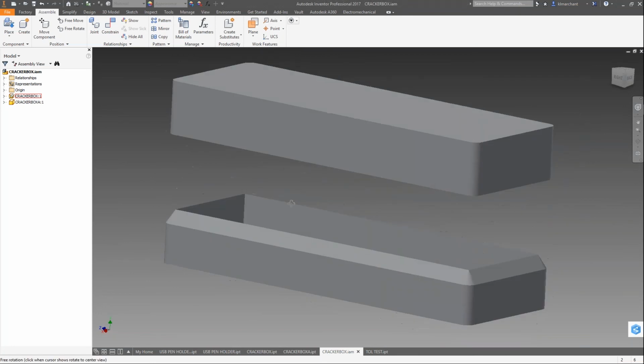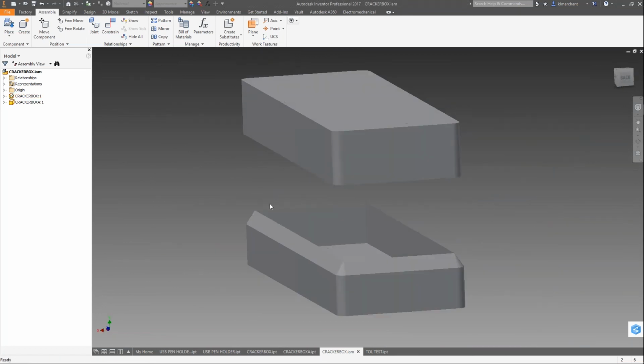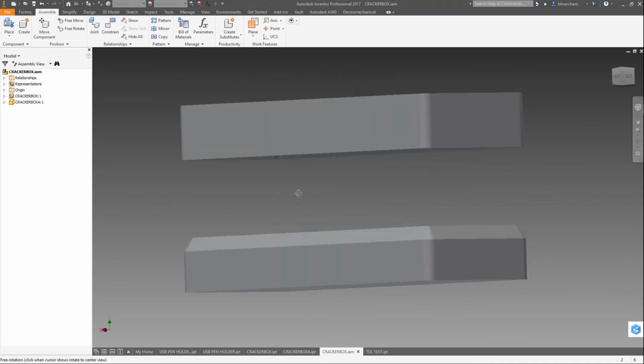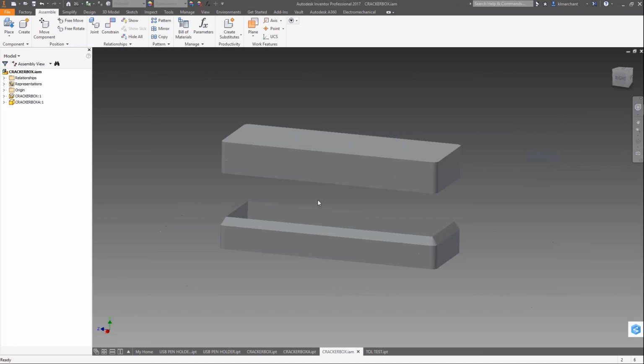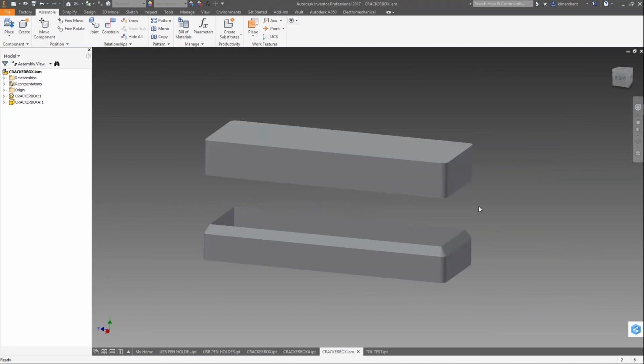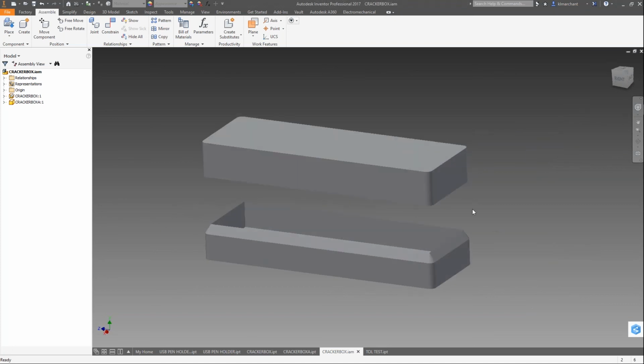If this was going to be machined out of aluminum or something, I could easily go 1/16, or even if it was going to be a steel, I could probably go thinner than that, being that the most pressure exerted on this box would be less than 200 pounds as it rolls around in a backpack on a race course.